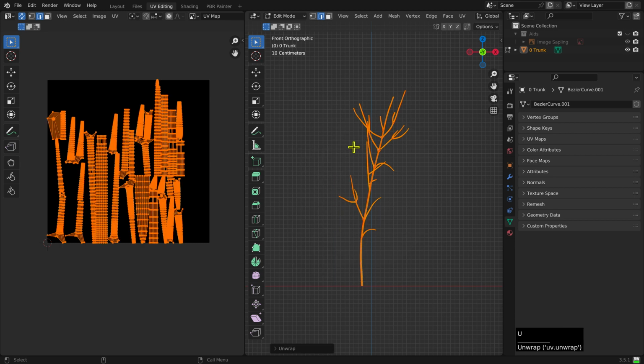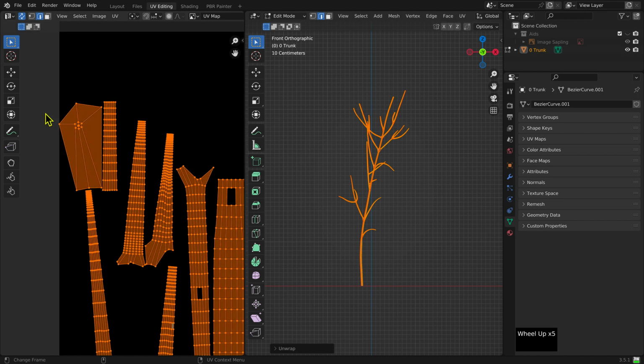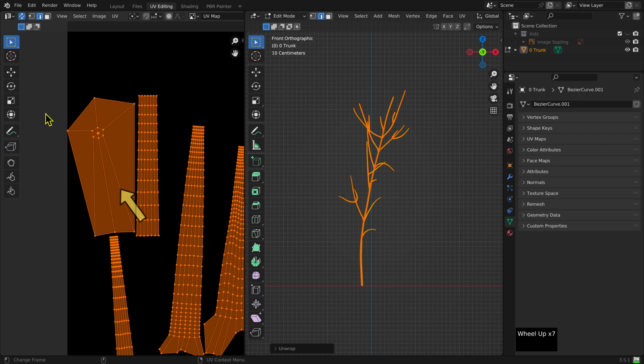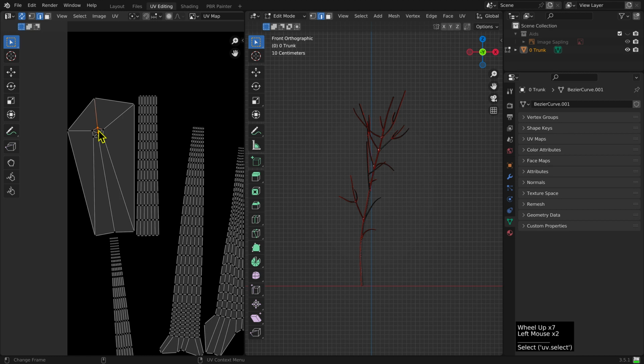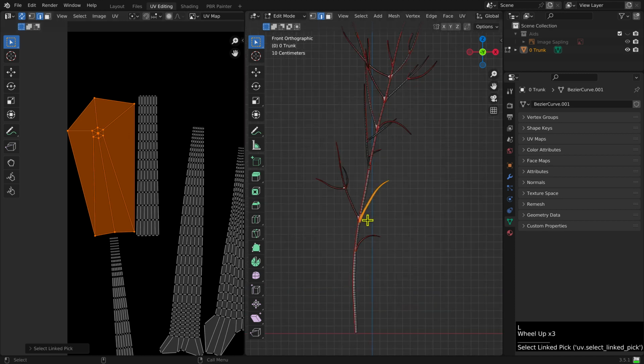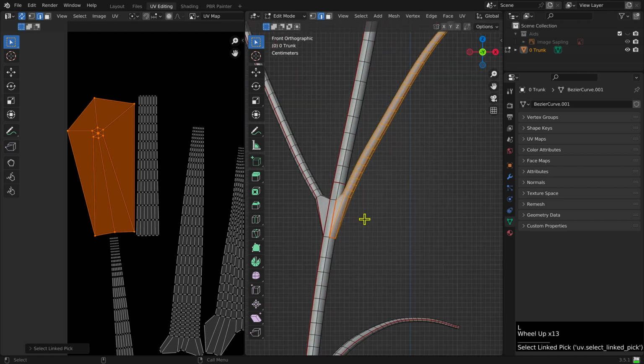In the UV editing window, check for errors. Here the UV map has not unwrapped correctly. Select the UV sync selection icon and select the UV island. Keyboard shortcut, select an edge, then with the mouse cursor hovered over the island, select the L key. In the 3D editor window, locate the island.